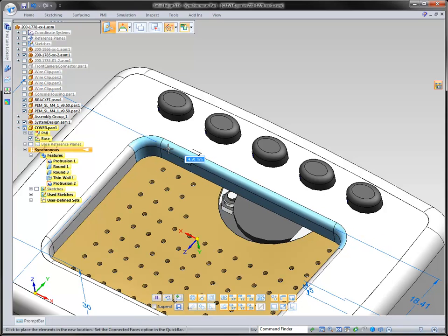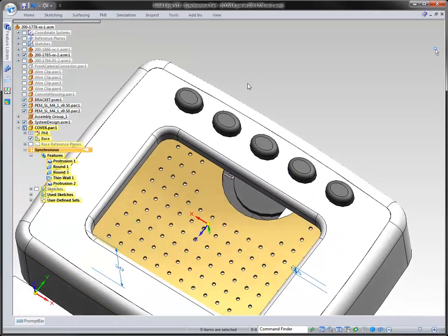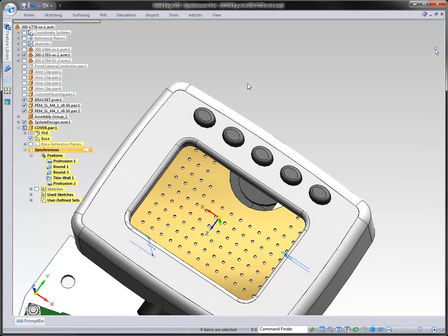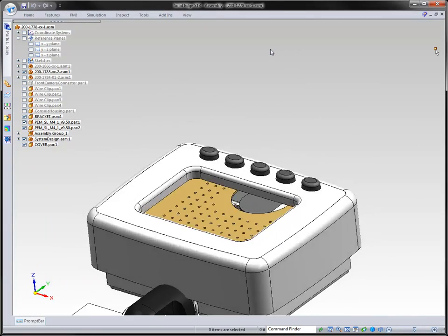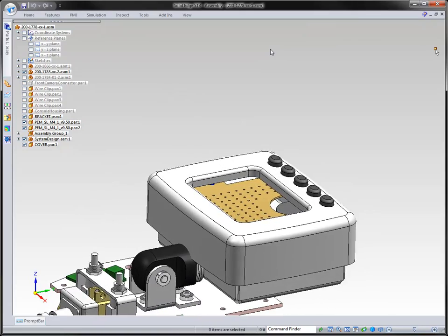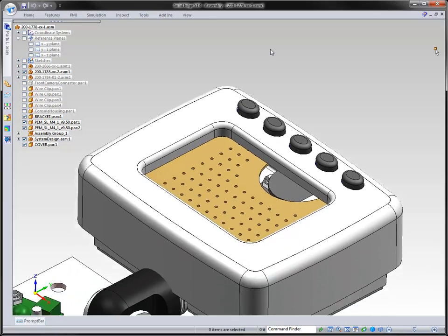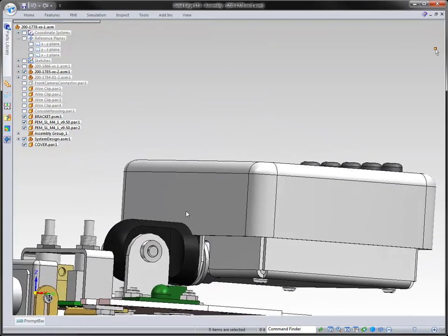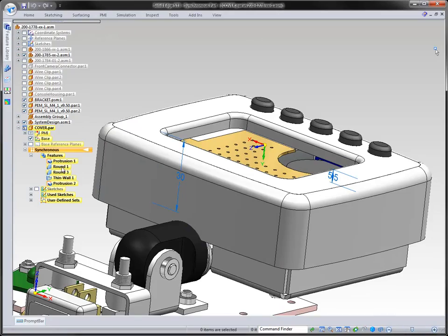And let's just put in 4.9, and you can see that we can precisely put that in there, and now we know we have a true fit and function of our part. So you can easily see how top-down design inside of Solid Edge is very easy. And we can also see instantly we have some information here that's also being interfered with, but that's real easy.